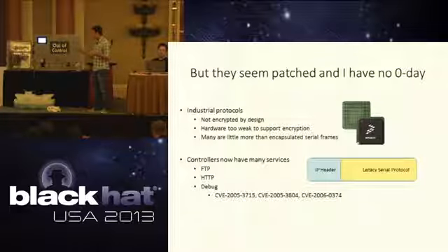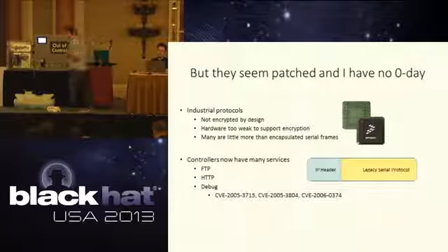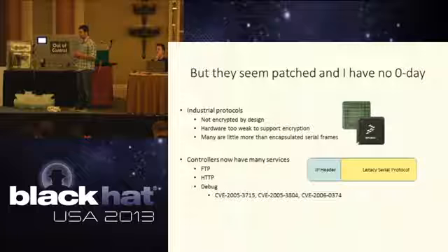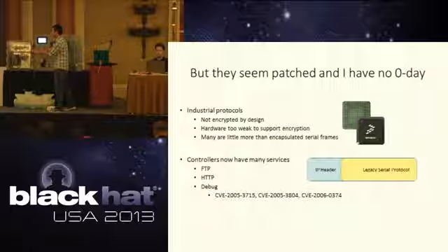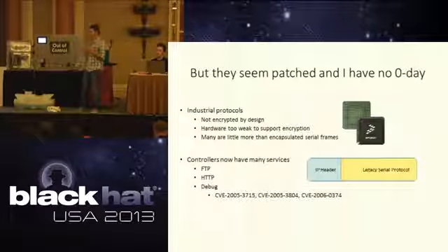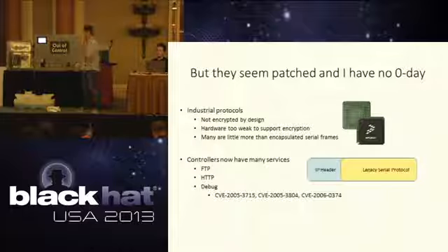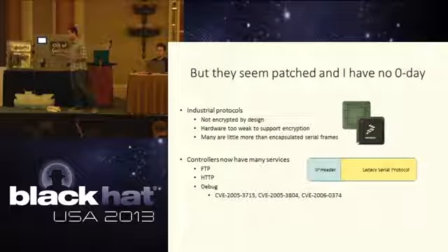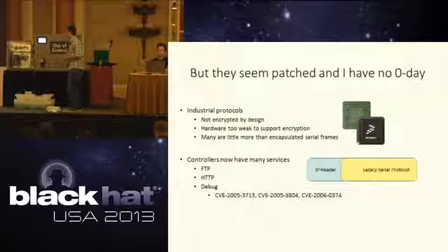Okay. So there's a couple of different things that we can do with a controller. One thing is that we can actually do binary exploitation of it, traditional buffer overflows and stuff like that, because a lot of these guys don't have the protections that you would see in a normal Windows machine, such as DEP and ASLR. These are just really old, simple machines. But what we want to do is we want to actually go after the protocol itself. We actually want to build a packet to tell the controller to drive its I/O without actually modifying the logic, just telling the logic to essentially be quiet and drive those signals ourselves.